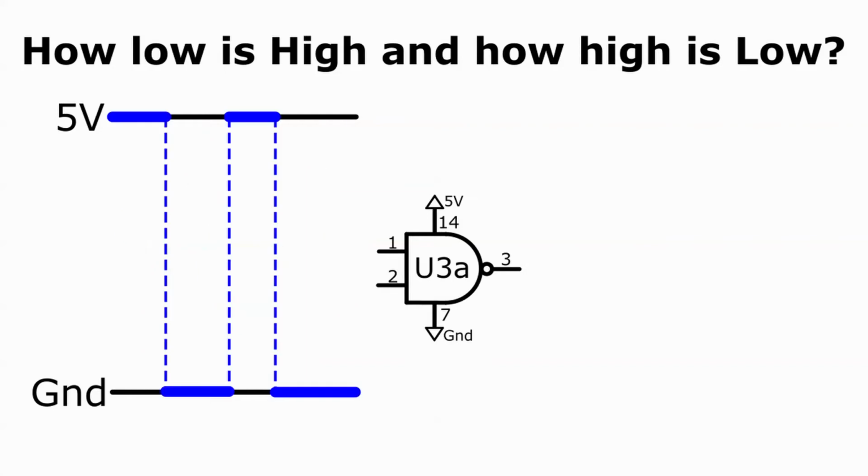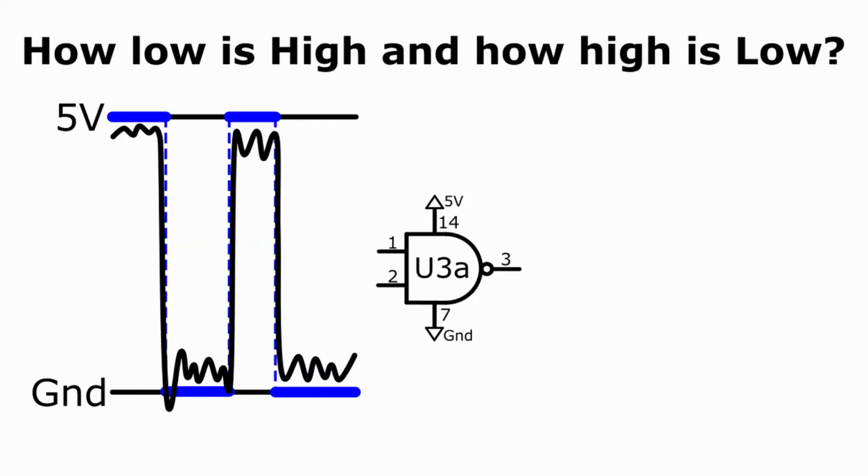The voltage in a digital circuit should look completely different. Ideally, it would be high or low, either at the positive supply voltage or at 0, as shown in blue. But that's unrealistic. Even the best digital circuit contains a bit of resistance, and the capacitance and inductance throughout the circuit will cause the voltage to be less than ideal. The voltage will oscillate. At times, it might even overshoot the high and low levels of the power supply.